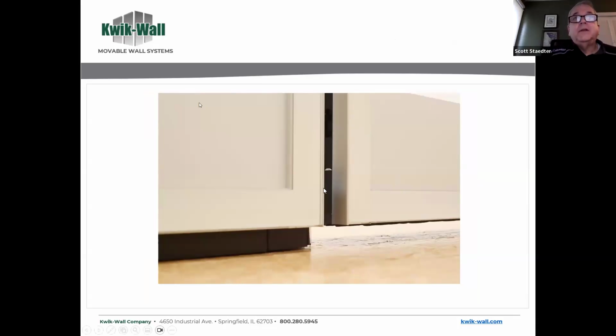this very little piece that's coming around the edge. And then it's back painted white. The interior frame is white as well, but it's back painted, and the glass is held in with a combination of glue and tape. So you have tape and glue, and the back paint is there to hide how that piece of glass is actually glued into the frame. And it allows there to be just a hairline of material between the two panels.